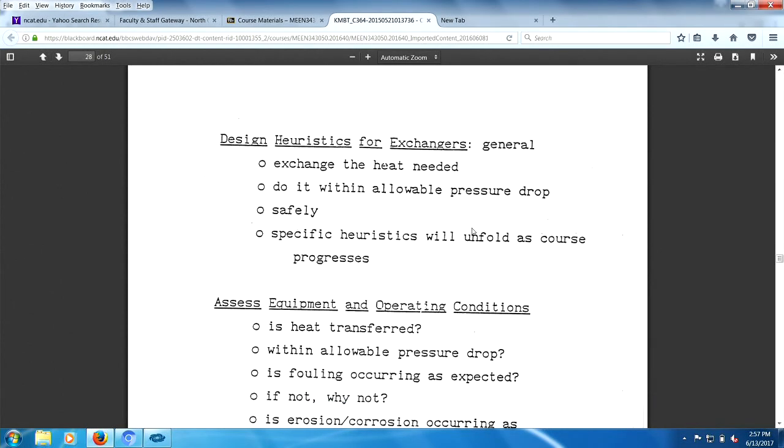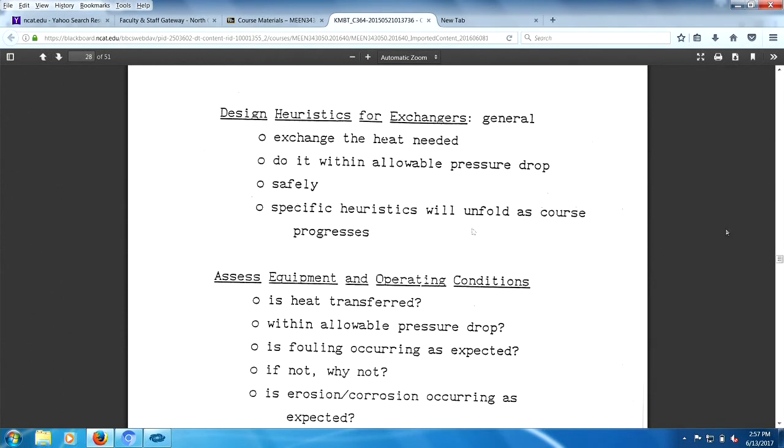So what the devil do we have here? The other thing I want to point out is allowable pressure drop. See the allowable pressure drop? That's not really what it says. It says utility bill. It takes power to run a heat exchanger. So I have pressure drop times volumetric flow rate. Very fundamental equation you should have learned in fluid mechanics. Again, flow rate times pressure drop equals power. Now, all of us pay a power bill at the end of the month, right? Our electric bill, that's a power bill.